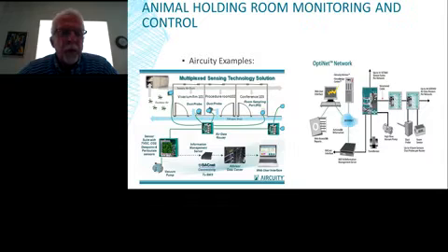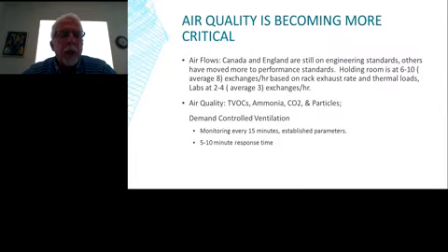So ramping up just before washdowns and then waiting until the particulate matter drops enough, and then coming back down to where it is within control. Also, with different stocking densities, you will get different CO2 levels. They are very good at monitoring that and looking at the airflow needs and everything that is related with that. As I mentioned, air quality is becoming more of a challenge globally.